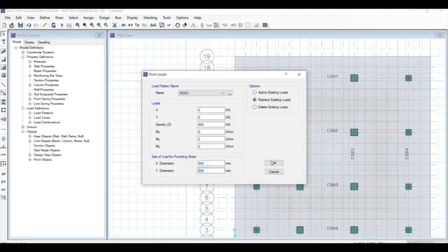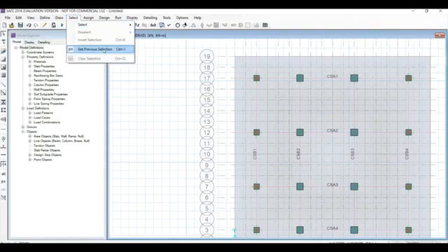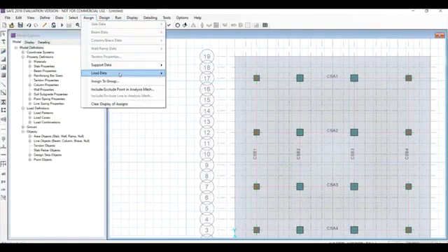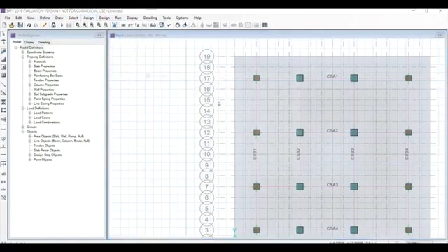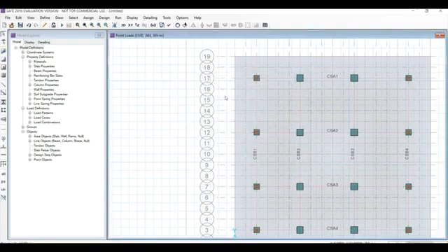So place the existing loads and then click OK. And again select get previous selection and again assign load data, point load, go for the live load and here give double of it, 1200, and then save and click OK. And again now select the remaining thing.